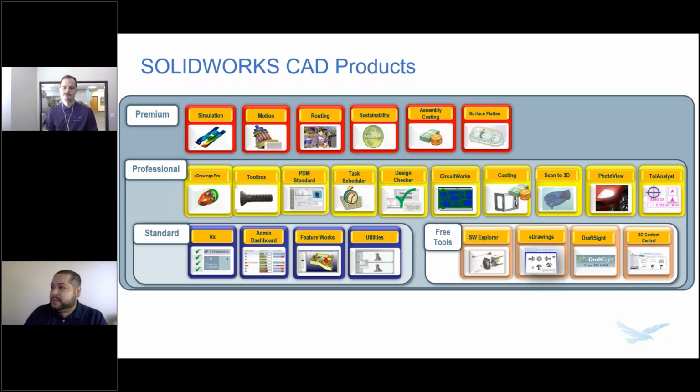But I did want to go over this one question that came up, which asked, and I'll quote it here, if I have SolidWorks Premium, does that mean that I have access to all the tools for simulation? So I just want to clarify that your SolidWorks Premium license gives you the capability to do linear static analysis and kinematic rigid body motion. So these first two tiles here fall under the category of the highest level CAD package that's available. So if you have that license type, then I definitely recommend going into Tools, Add-Ins, and turning on the Simulation add-in, which only gives you that structural tool.